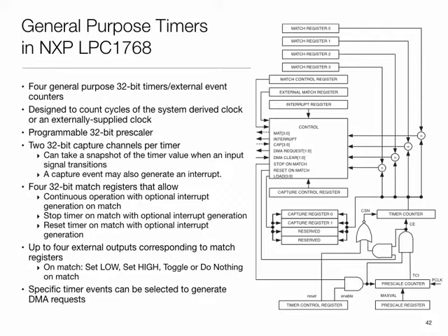If I want to timestamp an incoming signal, so for example, let's say I want to discipline my local clock from GPS. So I can take a GPS thing, take its 1 PPS signal, feed that to the capture channel. So every time the GPS signal comes, I'm going to get a value. I'll get the current value of the counter.